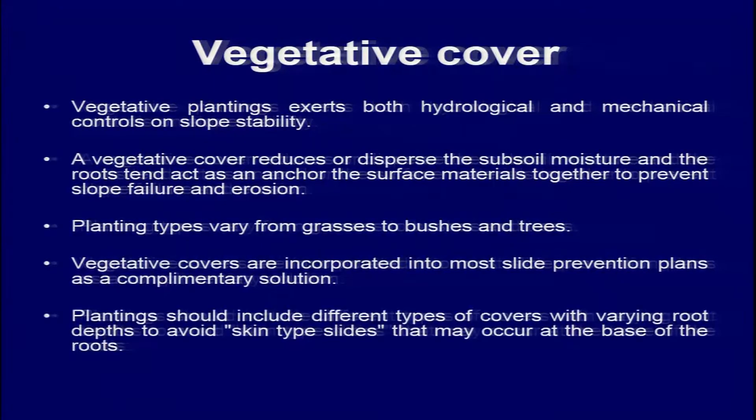But of course, if you are planting very heavy trees which can put additional load on the slope, that can also trigger the landslide. So one needs to be very careful about what type of vegetation we put or plant on the slope depending on the material.